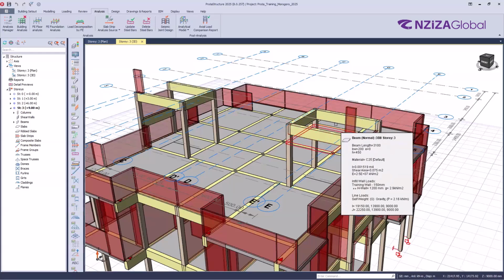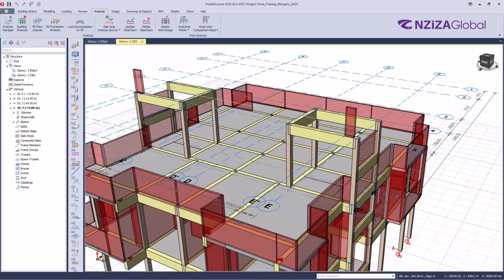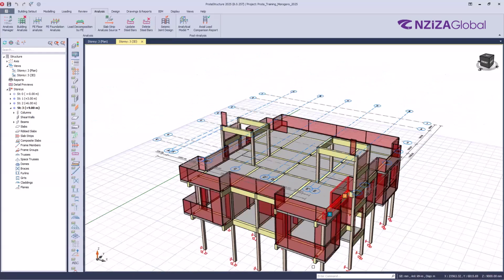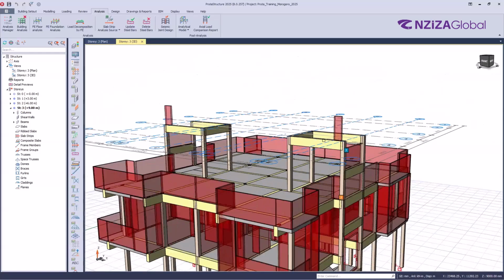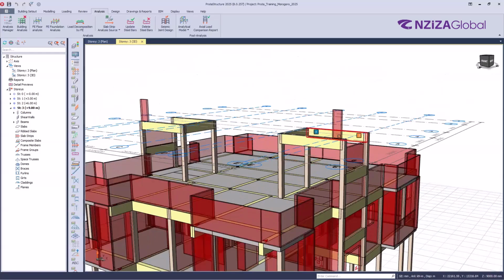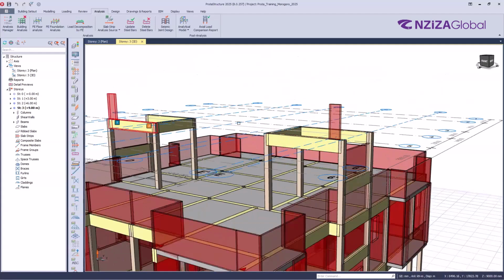Okay, so that's what I want you to do. You have already modeled story 1 and story 2. Add story 3. Elevate the columns and the beams along the stair. Then at the top here, model the roof members, truss, purlins, and put cladding. After doing that, now we will analyze again. Then after the break, we'll start the design. Okay, so go on, please, and do the same.